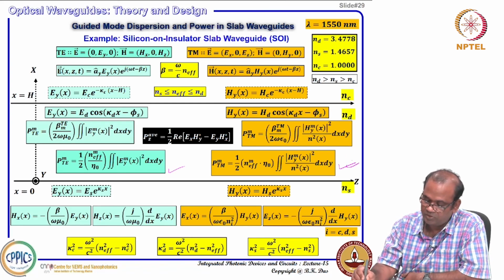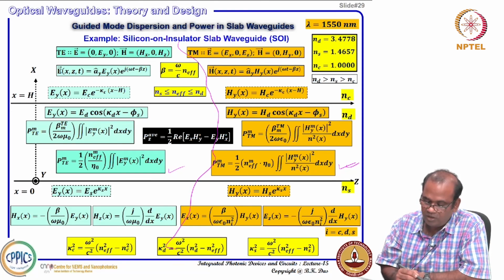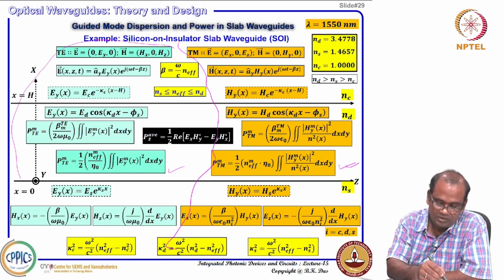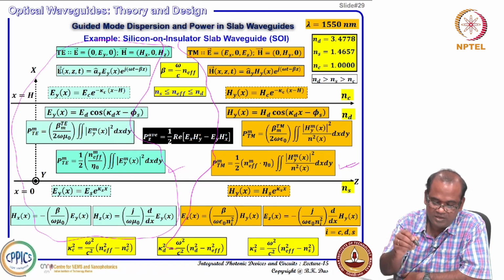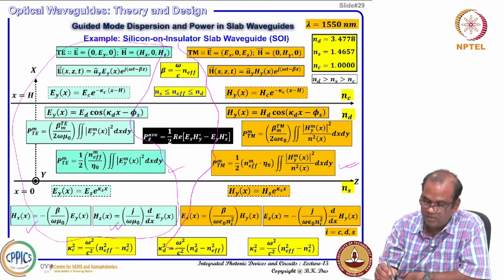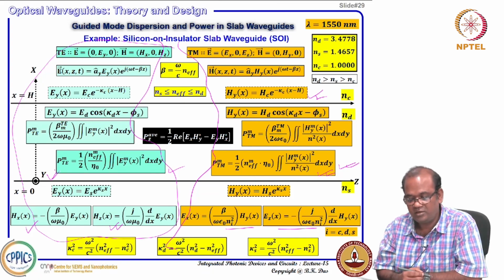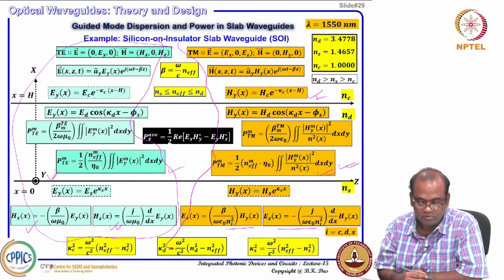This is the final expression. So, all this orange color part corresponds to the TM mode, and all the green color part expressions together are summarized here: all the electric field distributions and other components, the corresponding magnetic field. Here for TM polarization you have the solutions and corresponding electric fields, and how much power it will carry can be calculated, and for TE polarization also how much it will carry, we are also able to express.